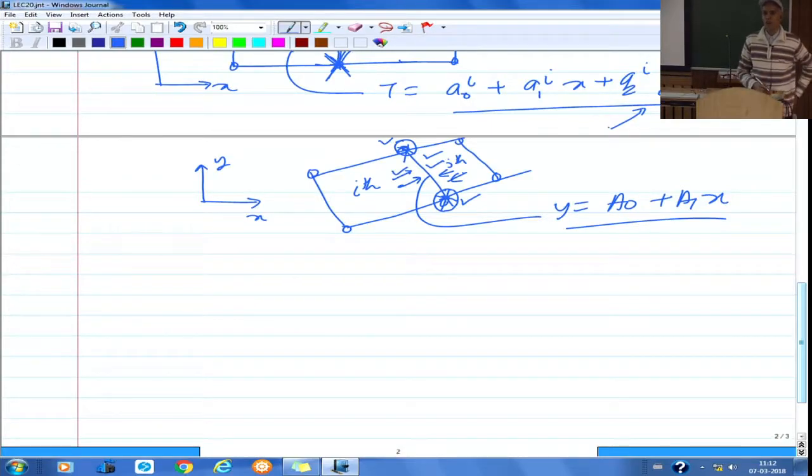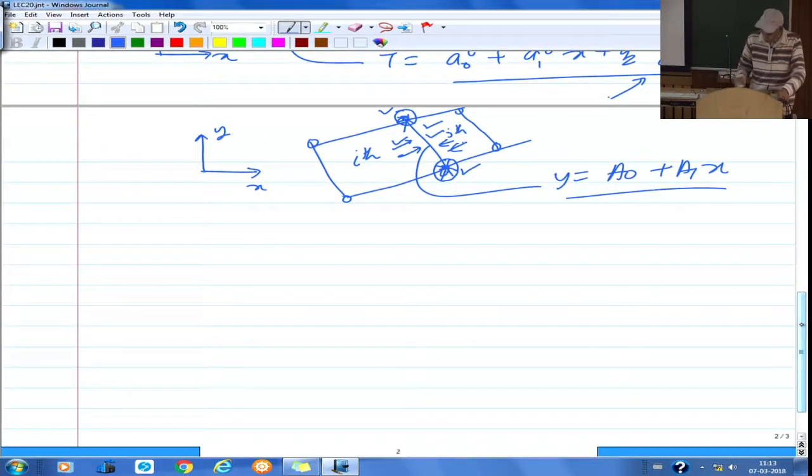So, whatever formulation you have for the 2 noded Timoshenko beam element, rather than exactly integrating the shear energy, you actually use numerical integration with single point integration, and whatever total stiffness you get after combining the bending and shear, if you use that, then it will not give locking problems, but then that can only be used for thin problems. For thick problems, it will actually underestimate the stiffness and therefore overestimate deflection. So, that is the problem with reduced integration. Maybe we will discuss this when we also discuss some plate bending problems. So, that time we will discuss more about this.